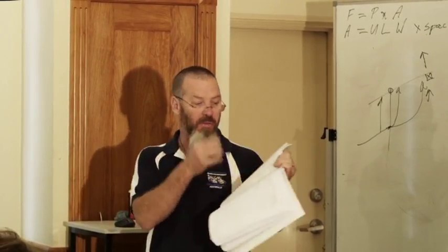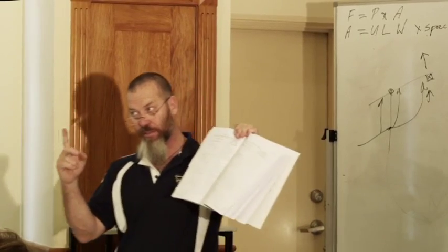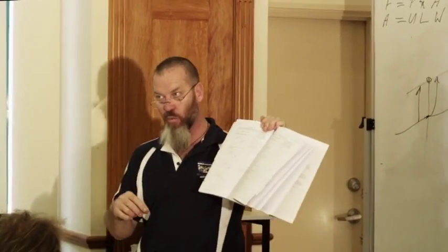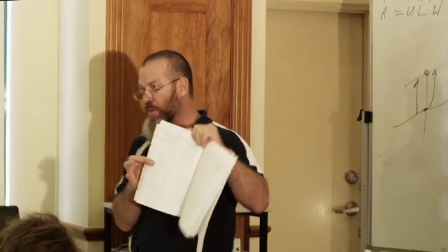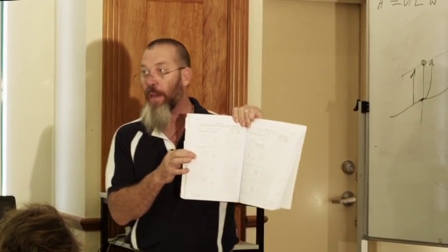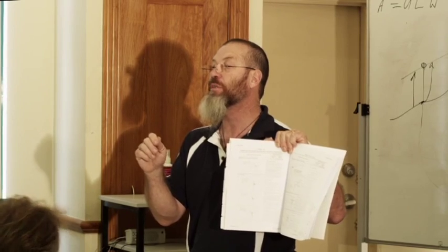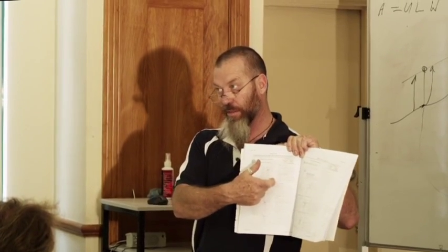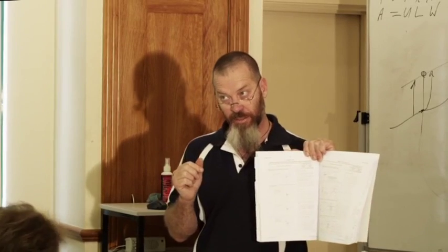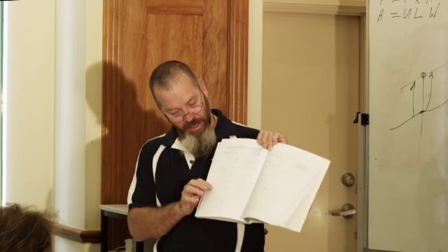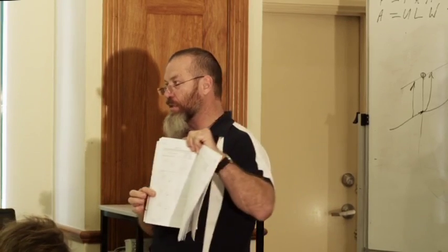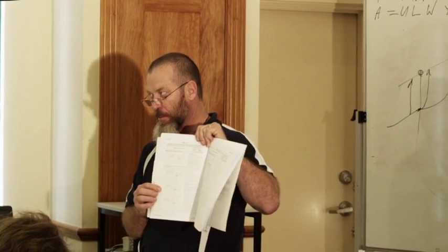Now, Type A is where we've just got 2 effective skew nails, not ones that blow the side of the truss out or the rafter out. Type B is triple grips, TGRs, TGLs, not triple grip universals. You know your universal triple grips? They don't have 2.9 kilonewtons of resistance, they only have 2.3 kilonewtons of resistance. Don't fall into that trap. Be careful. Type C is basically cyclone straps. They're a proprietary fixing as well, but it's a cyclone strap.